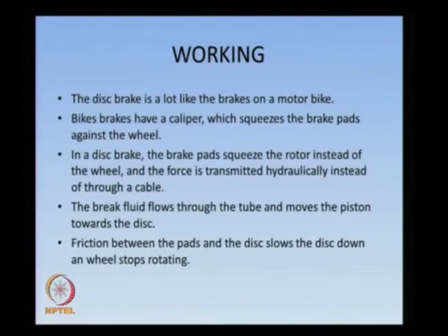Working. A disc brake is a lot like the brakes on a motor vehicle. Brakes have a caliper which squeezes the brake pads against the wheel. In a disc brake, the brake pads squeeze the rotor instead of the wheel, as the force is transmitted hydraulically. The brake fluid flows through the tube and moves the piston towards the disc.